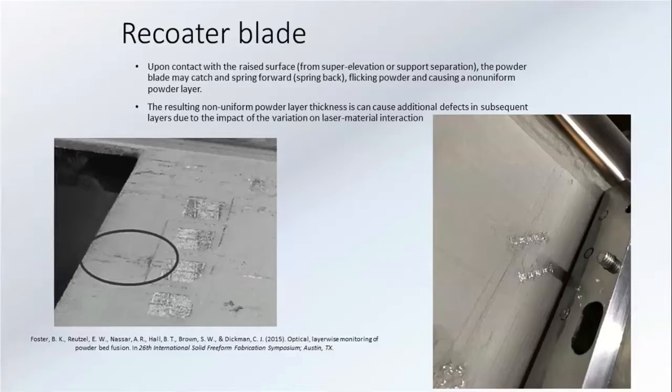On the right is typically a harder recoater problem. You can see that little wavy feature in there, and that's the recoater kind of bouncing as it goes along. So it hit something and there was a little bit of reverberation bounce in there. Again, it's causing not a smooth layer. So your ultimate goal is a beautiful smooth layer every time.